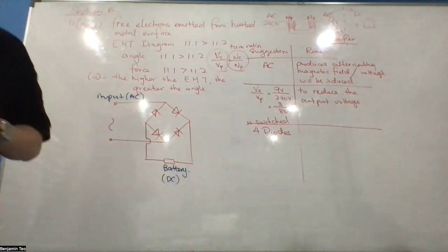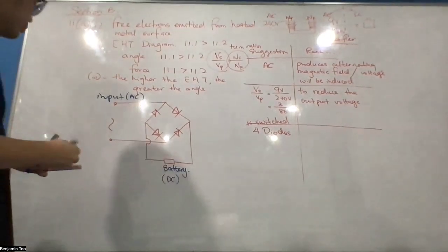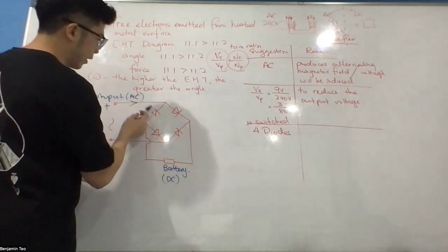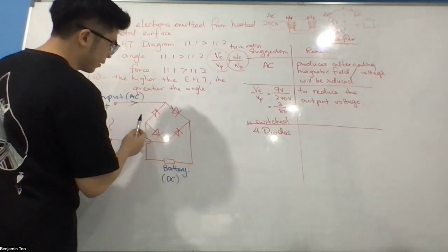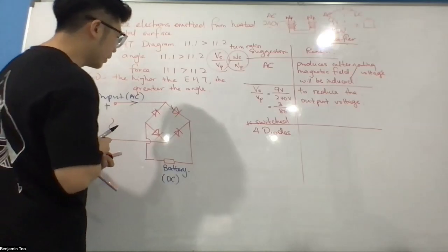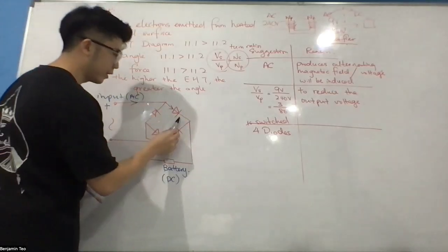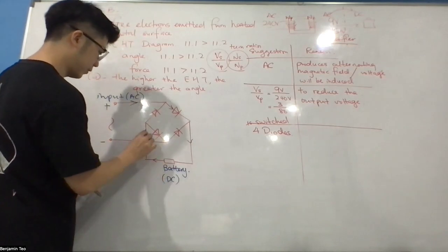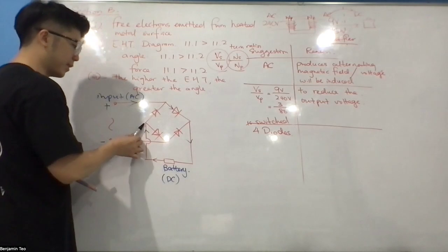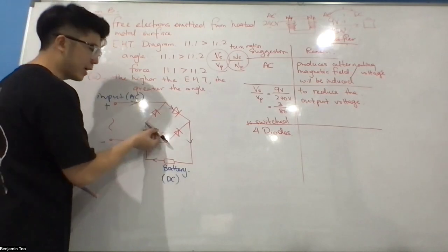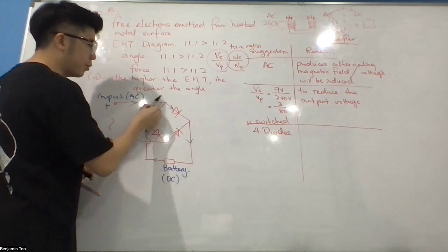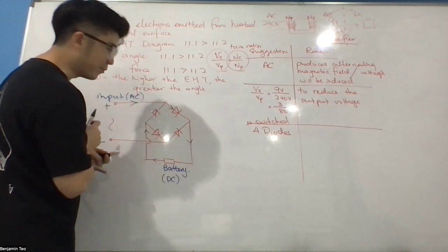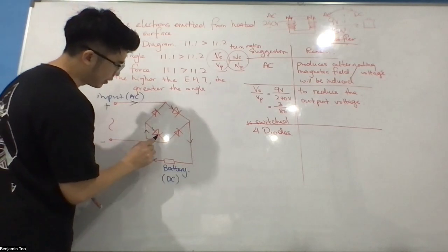How is this DC? Remember we labelled the current positive and negative. The current follows the diodes, and remember it cannot flow against a diode. So here the current goes like this. Coming to this point, it can flow up or down, but it cannot flow back. You cannot flow to where it came from. So the only choice is down.